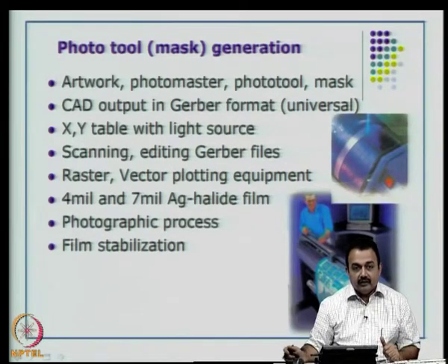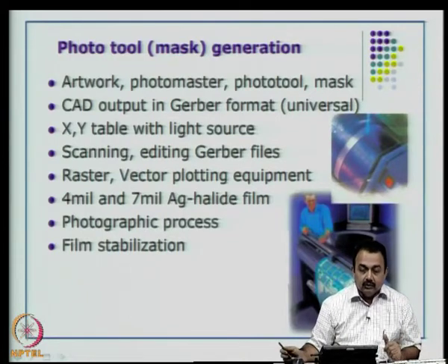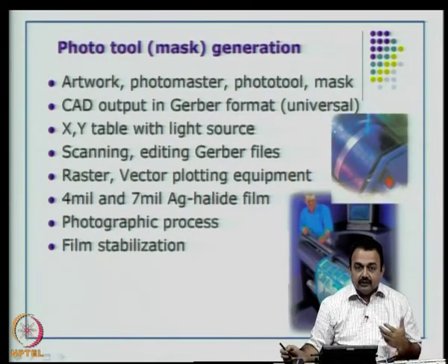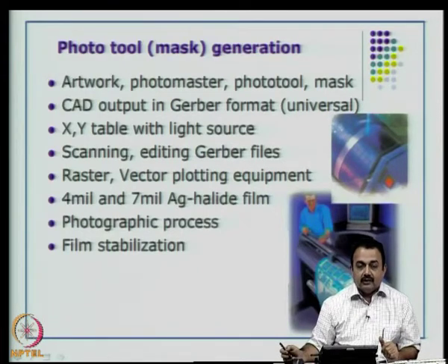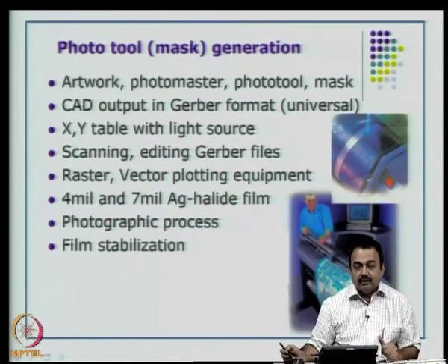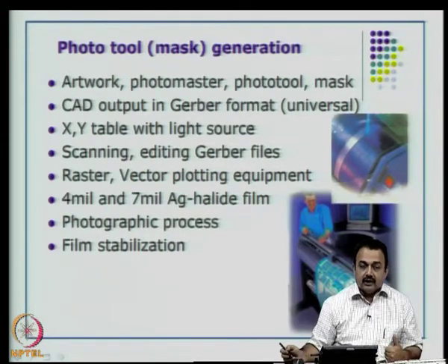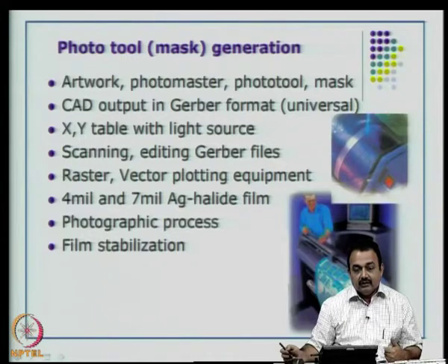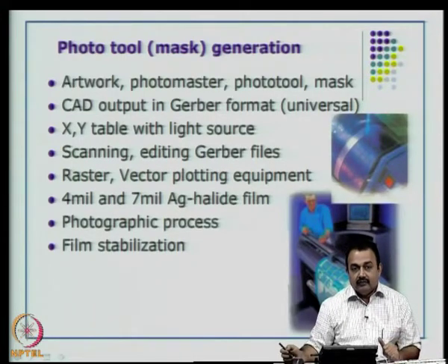Otherwise, you have to look for a vendor who will create this photo tool or a mask and then give it to you, or sometimes the manufacturer has this photoplotter which will be in a clean room area, because you are going to handle very sensitive materials like the photofilms, and then this mask, whether it is a single layer or a multi-layer electrical layers, and then as I said, all the various other utilities like a solder mask layer, a legend layer and so on can be generated with the photoplotter.